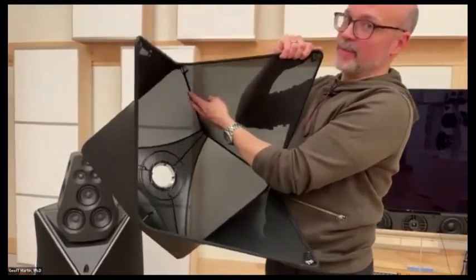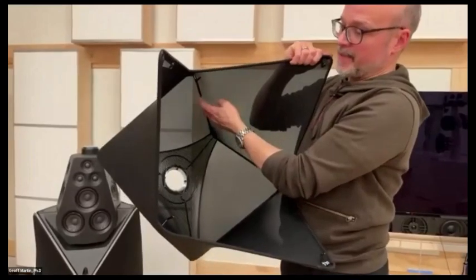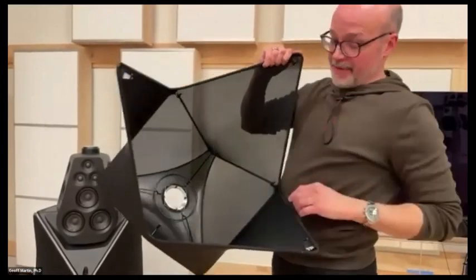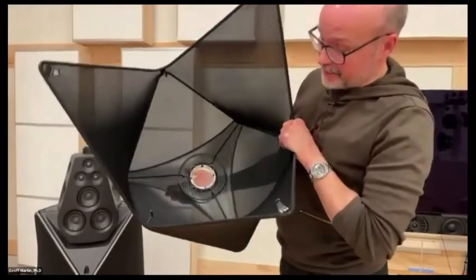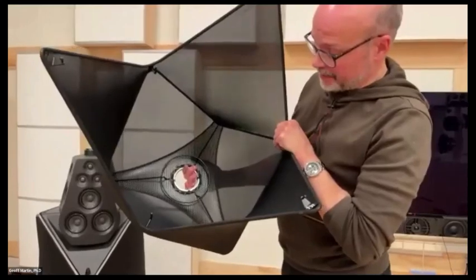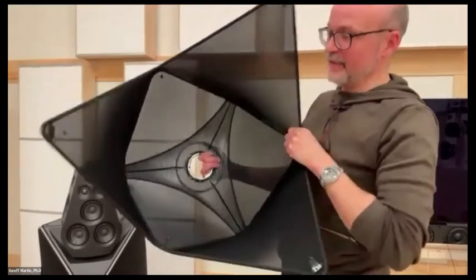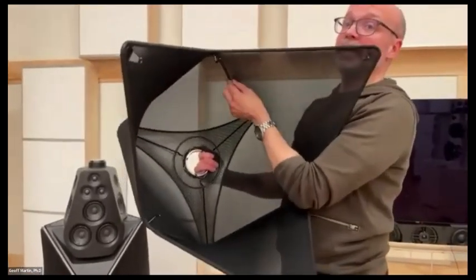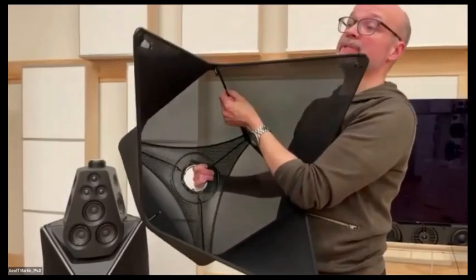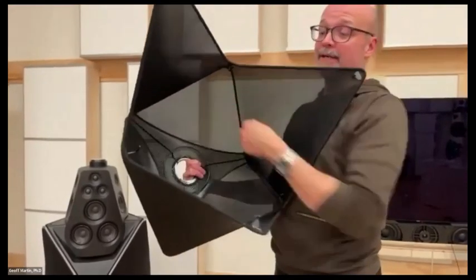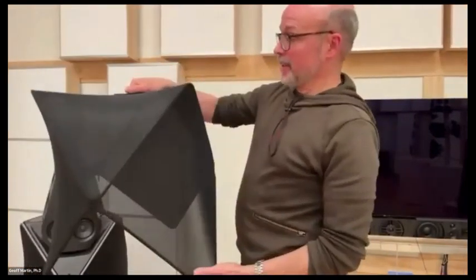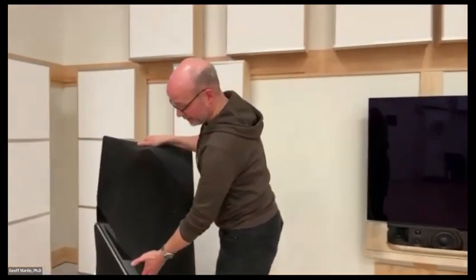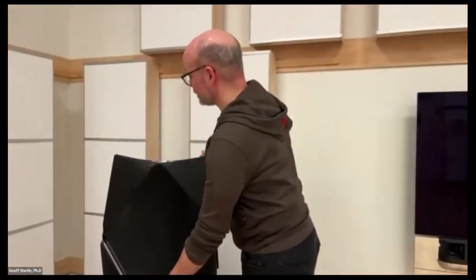However, because we're using beamforming from these tweeters, this becomes a huge problem because it affects the phase relationship of the drivers out in space and causes our directivity to go a bit out of control if this wire is too big. So we gave the designers a maximum allowance of 5 millimeter diameter on this wire. So they had a bit of a challenge there as well to make sure that they could design a hat or a grill that could live on top of the speaker without messing up the directivity control that we wanted to implement.